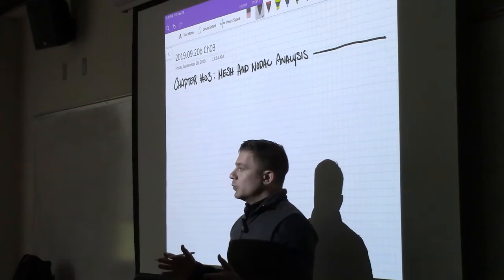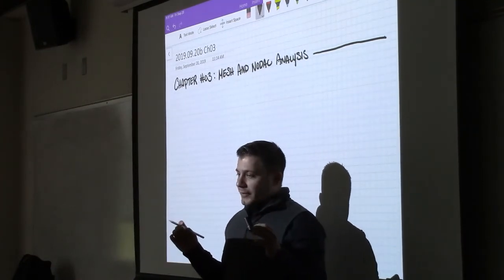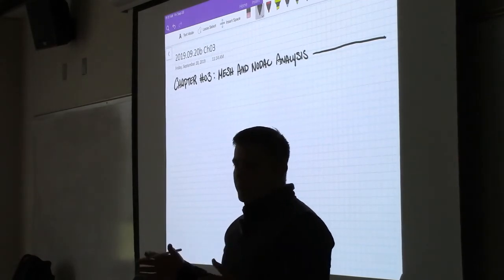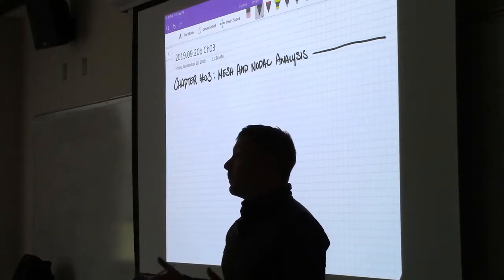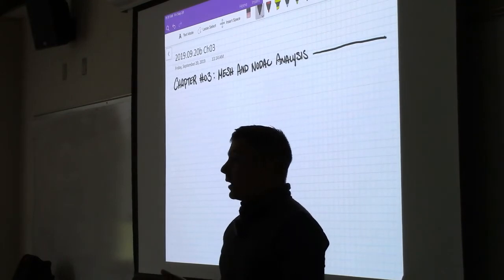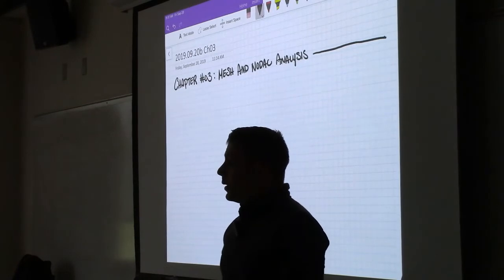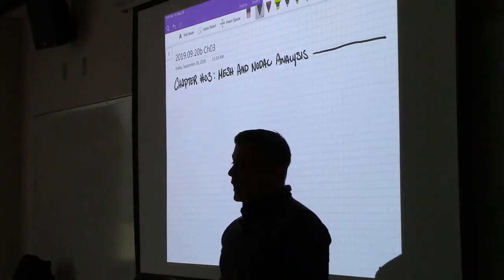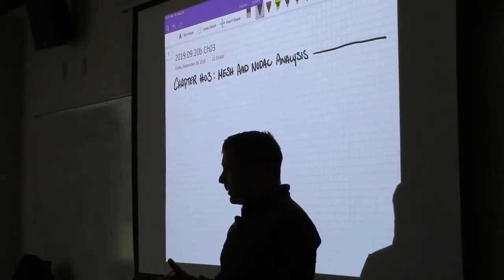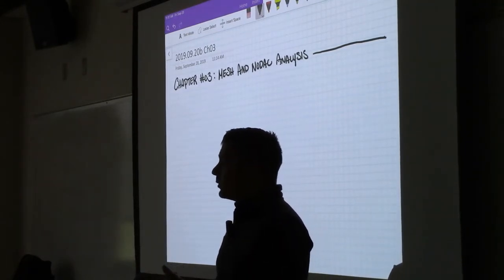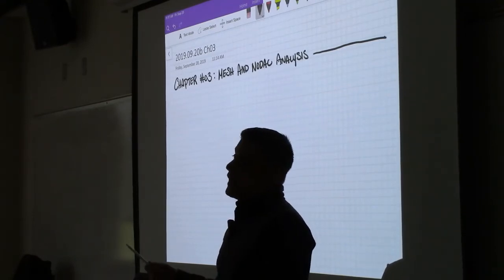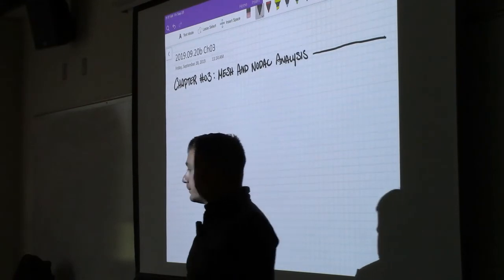Okay, you have to get everything exactly right, signs are important, and the matrices will get big relatively quickly. We're not going to be doing any huge examples like 10 by 10 or 20 by 20 or anything like that, but we will get into the realm of like 5 or 6 node circuits where the admittance matrix, which we haven't learned what that is yet, will be 5 by 5. So, that's 25 elements that you got to fill in.